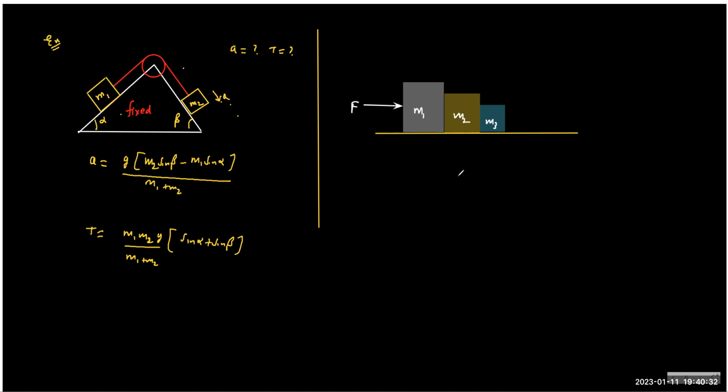Let's say if I slap your left cheek, will you draw the FBD of the slap on the right cheek also? No. The force, if it is applied to the first surface, acts there only. What gets transferred is not force. What is transferred is the contact force, which is due to the other surface. You cannot create your own laws of motion in which you transfer the force everywhere because you feel so. So draw the FBD of M1, M2, M3 as per the laws of motion.